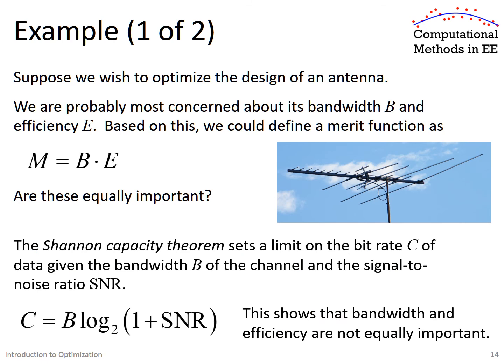So there is what's called the Shannon capacity theorem. And that's the equation at the bottom here. The capacity of the channel, so think of that as bits per second, although there's a bit more of a story behind that, is the bandwidth, that's B, times the natural log of 1 plus the signal to noise ratio. And that'll tell us the theoretical maximum bits per second that a channel can support.